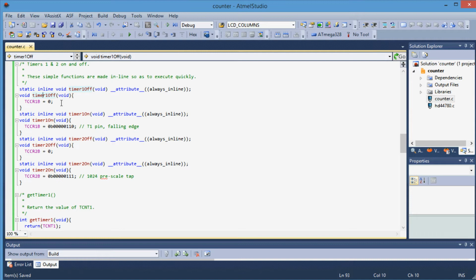And what return does is it goes back to the stack and removes the value of the call location and puts it back into the program counter, so then the microcontroller can go back to where it was called from and continue on. And that way that piece of code gets used over and over. You can call it many times in different places in your software and only use one piece of code instead of having to write that code many times and actually using up too much memory that way.